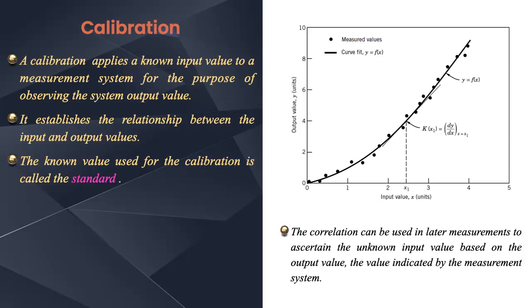Let us say we want to use the load cell in an experiment, and we calibrated the load cell and obtained the calibration curve. We want to know the load, or the force in any given system, that the load cell is going to measure. When we connect it as part of a measurement system, all we are going to record from the load cell is its output, in our computer or using a data acquisition system. The output that we record is going to be in volts.